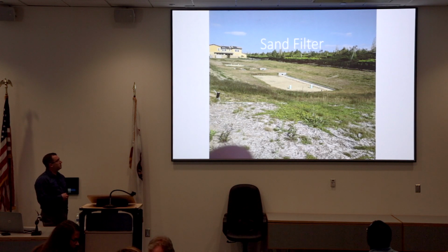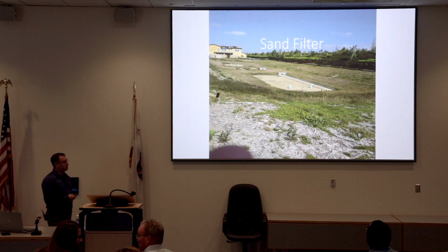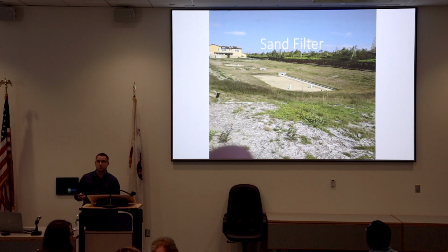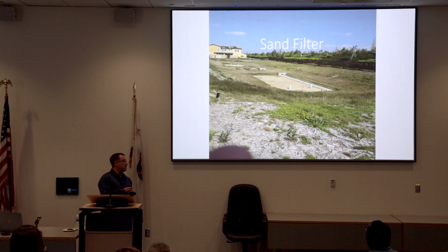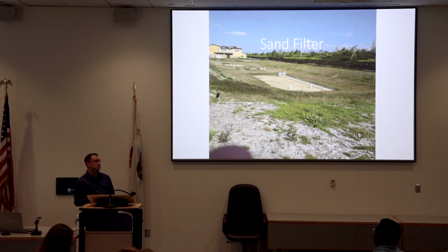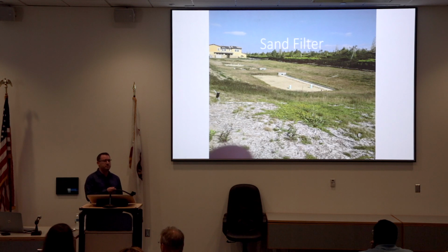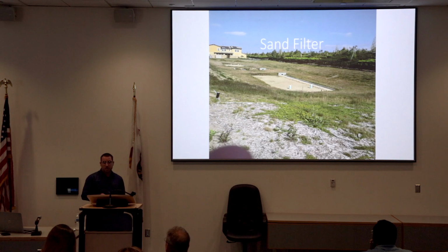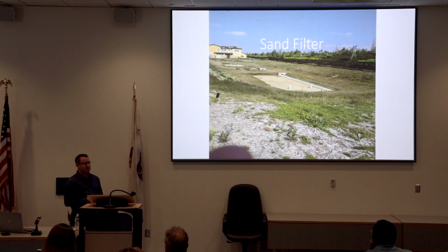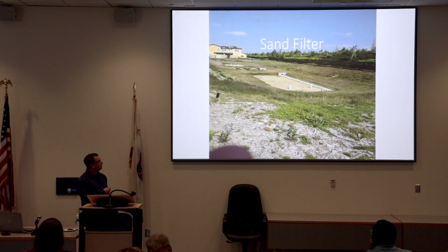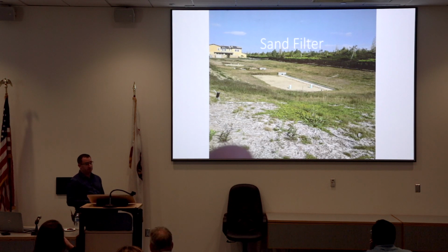And this sand filter is actually done very similar to what David described before lunch, which is there is kind of a choker on the system. So you have, I think it's a 48-inch pipe that comes down the street for this system, and they choke it down to an 18 or a 24 to get all of the low flow to come into here.